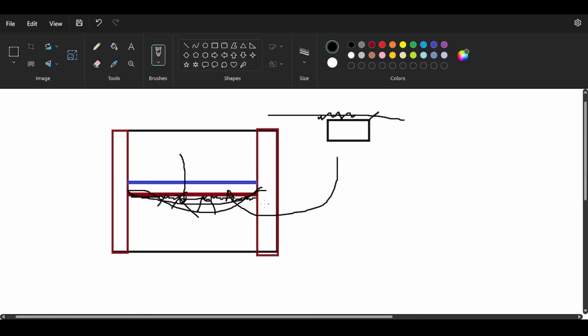What I'm saying is, I could have a beam whose height is 300 millimeter, and then of course, since it's 300 millimeter, I'm not going to have full bricks. So what ends up happening is I put the bricks of 200 millimeter height and 200 millimeter depth, and then I select a brick of 200 millimeter height and 100 millimeter depth, okay? So it's thinner. I rotate it and place it on top of here.